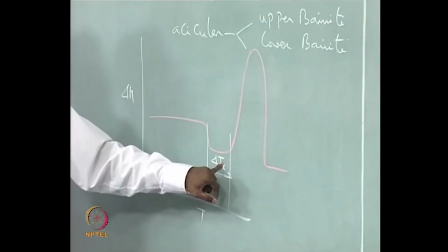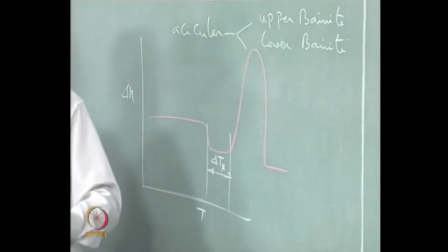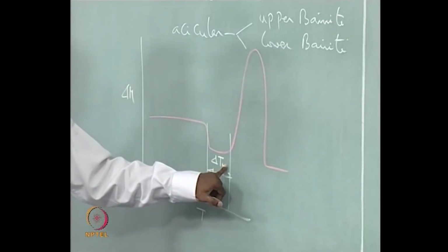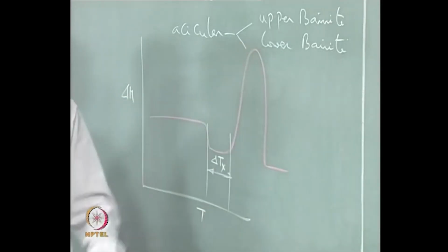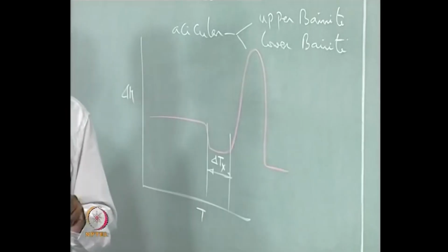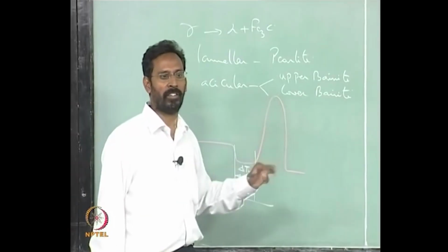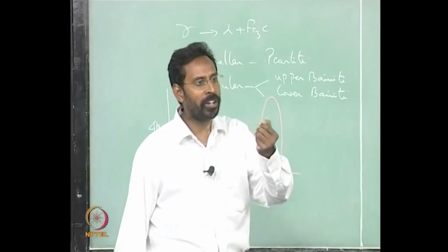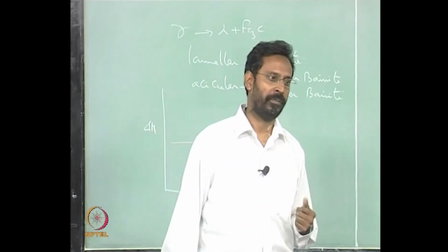So many people do that. In fact, all the shapes of normal glasses that we talk about also are more or less done like that. In a liquid state they do it and then freeze it. So similarly here you can do that, shape it and then further heat it if you want, so that you can crystallize, and in fact you can control that crystallization by controlling the temperature and time of crystallization, so that you can induce nanocrystals in a glass.